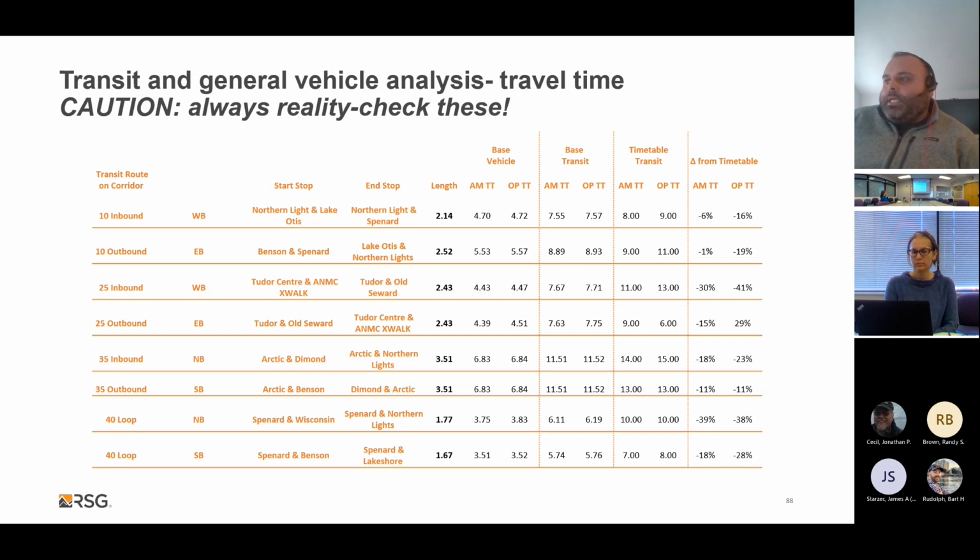So a quick note here is that the demand model may not show a lot of the variation in these unless the different scenarios have different congestion effects or notably different routing or other configurations. So the big thing here is that you don't necessarily want to look at an intersection level, you want to look at a corridor or at the route level.